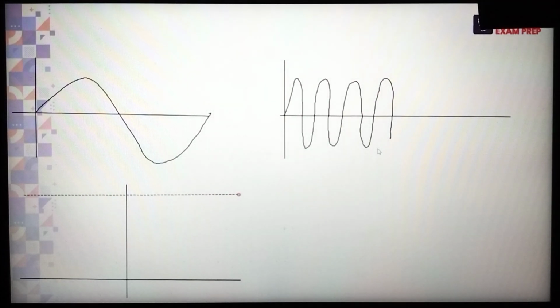Because we are giving sufficient time for accumulation and sufficient time for inversion. After that it will start depletion, maximum depletion, and finally it reaches this case. This is the VT. So already I have given: this is the accumulation, this is the depletion, this is the inversion, and this is called strong inversion. But in case of a high frequency signal, it is negative, then it will reach positive, then again it will reach negative, very fast.